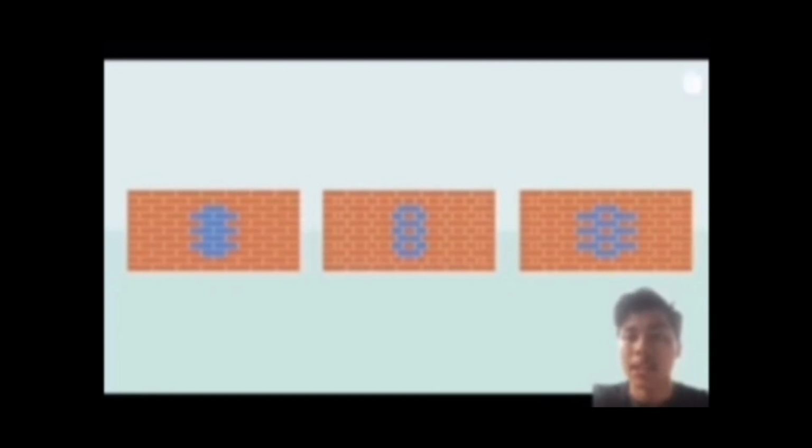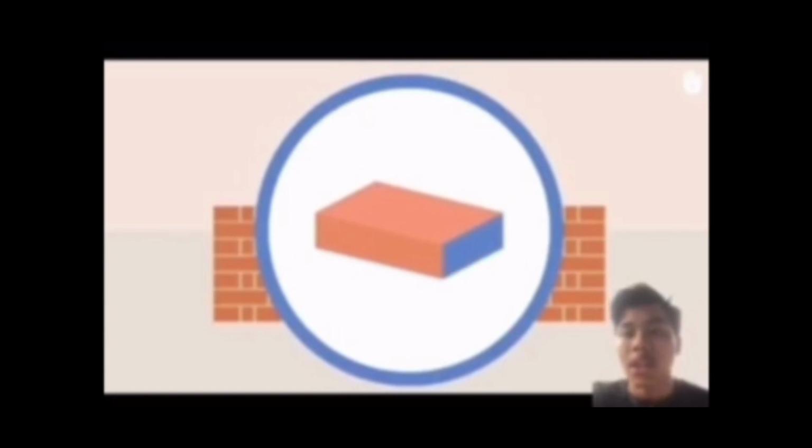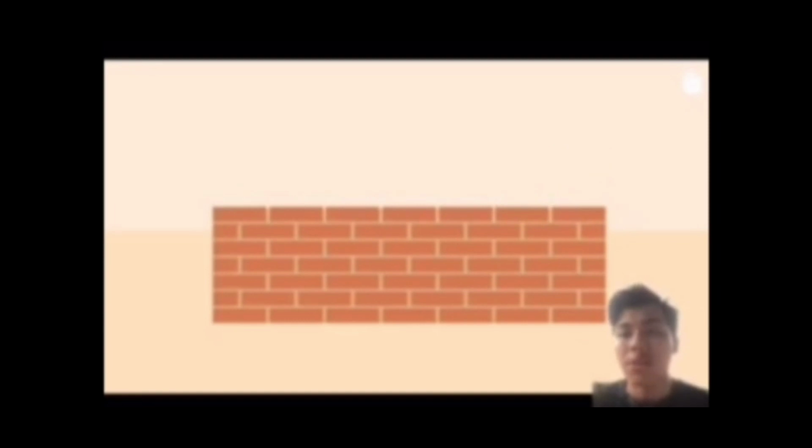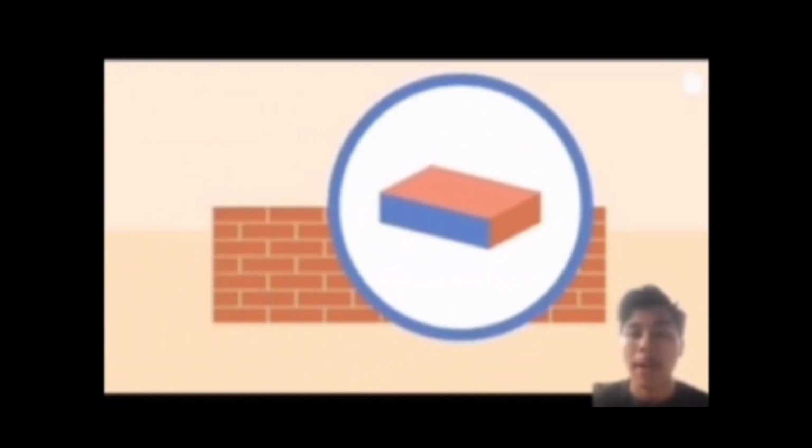A mortar bed is a layer of mortar on which a course of bricks is laid. A perpend is the vertical layer of mortar at the joint between two bricks. They ensure that bricks in the same course are held together. A queen closer is a brick cut in half lengthwise. The quoin is a corner brick where two walls intersect. An essential rule which everyone follows is to always offset the perpends of neighboring courses.